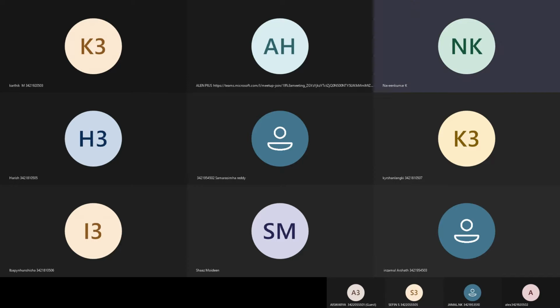You don't miss the sequence. The first thing to be known is analysis. After analyzing, you choose the desired shape of the steel section. After that, you go for the type of connection you are going to follow, whether it is a bolted connection or a welded connection.